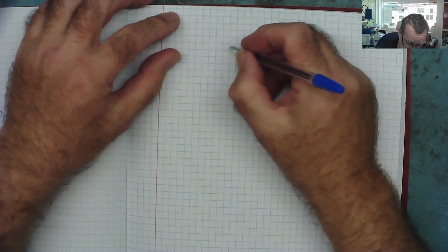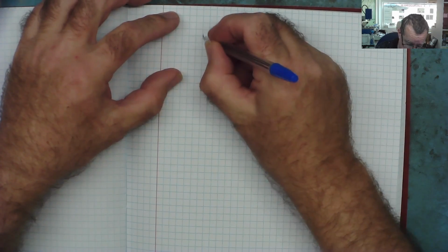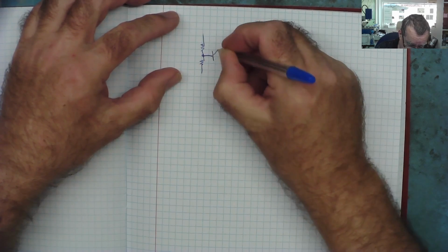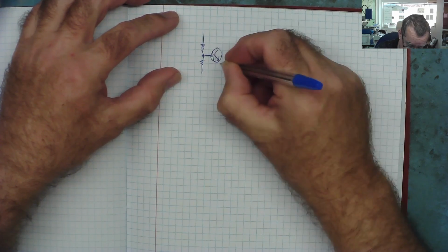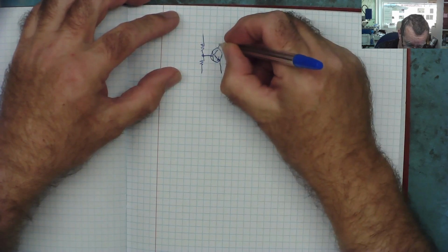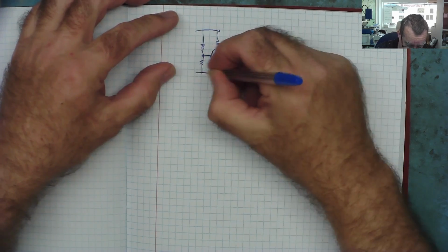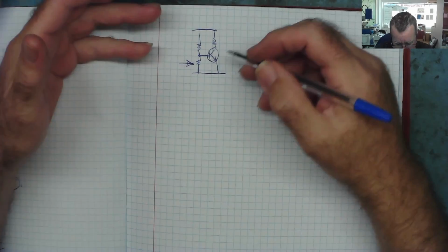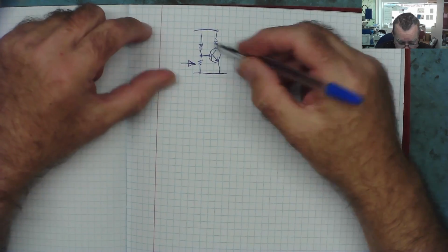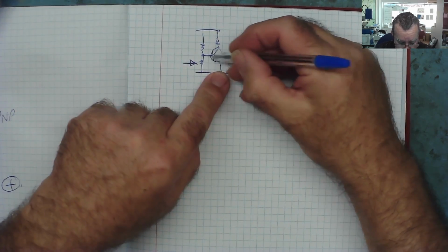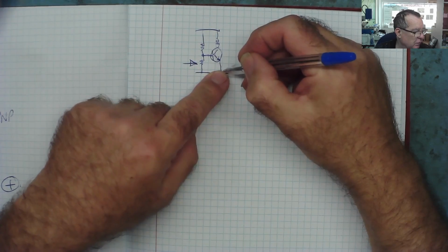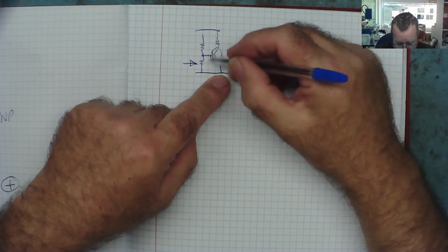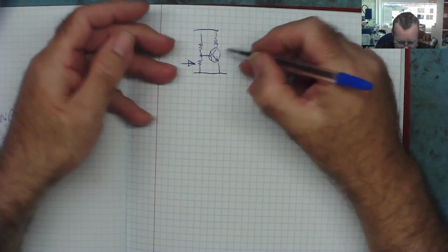So you can sometimes get circuits similar to what I've shown you, where you have resistors on the base. I'll draw an NPN transistor again. This type of circuit. And this resistor can be a low value. It can sometimes be a very low value. And in this type of circuit, if you measure across the base emitter, you'll probably see a short or near to short. And in fact, it's the base resistor that you're seeing. The only way to find that out is to take the transistor out.